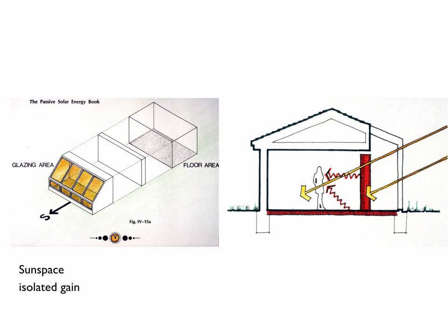This sun space then becomes like a servant, you might say, in Kahn's distinction between servant and served. So the sun space is the servant. The rooms that it heats become the served spaces. The sun space has lots of constraints on what it can be, and then it frees up the served space to have a lot more flexibility, although we do like to still see some thermal storage in some of those spaces. The heat transfer is by radiation primarily, although it can certainly be by convection.